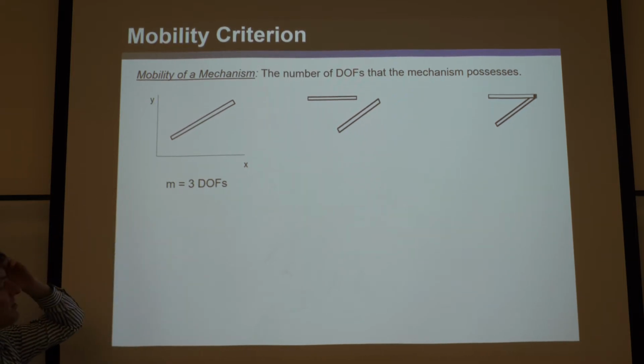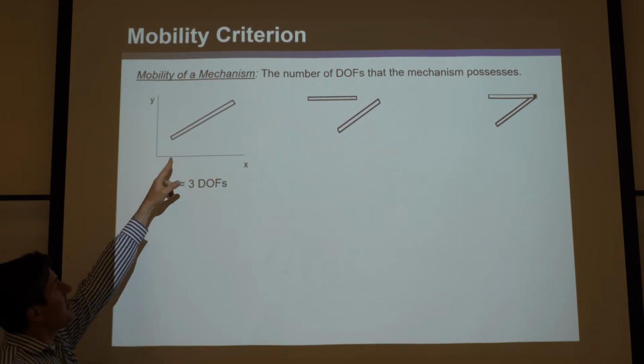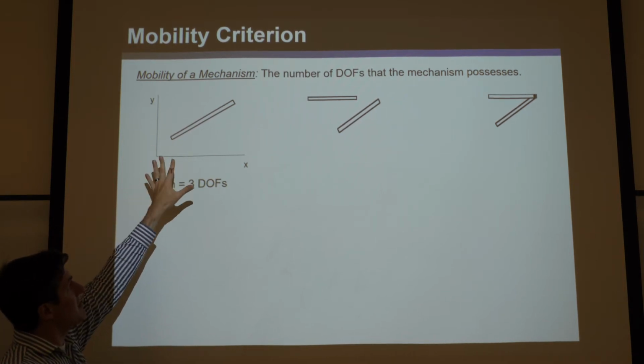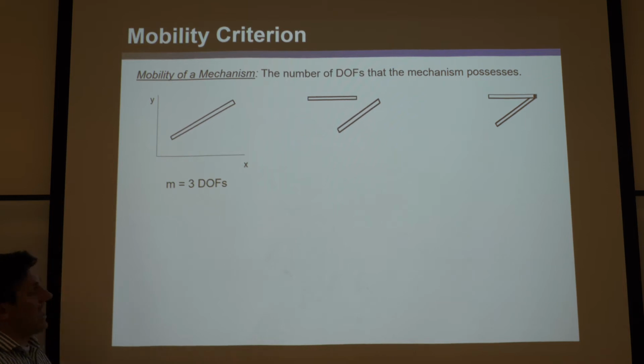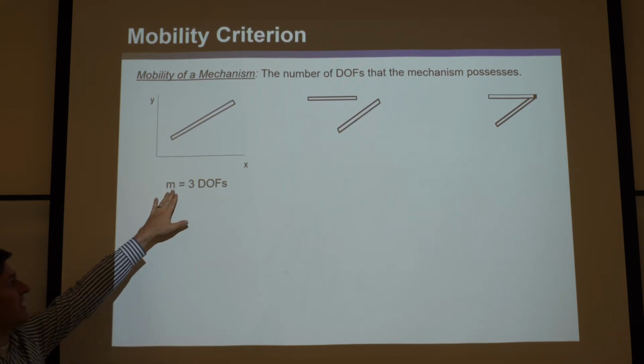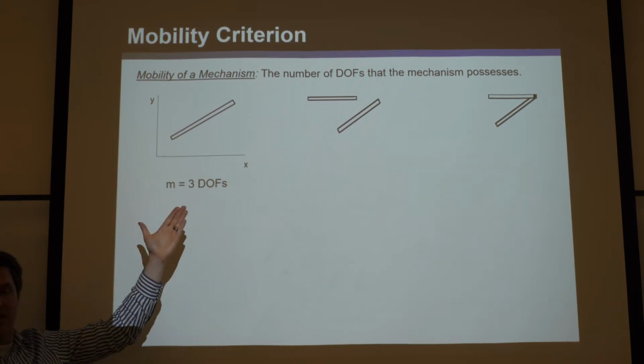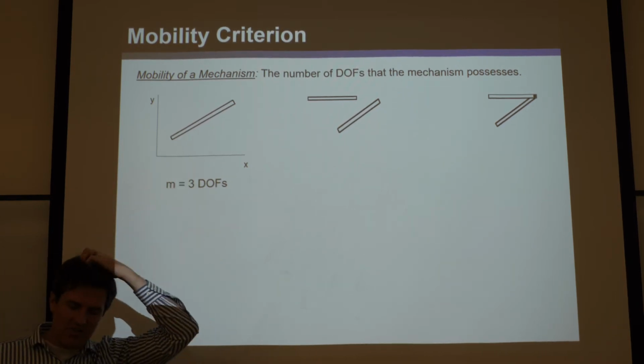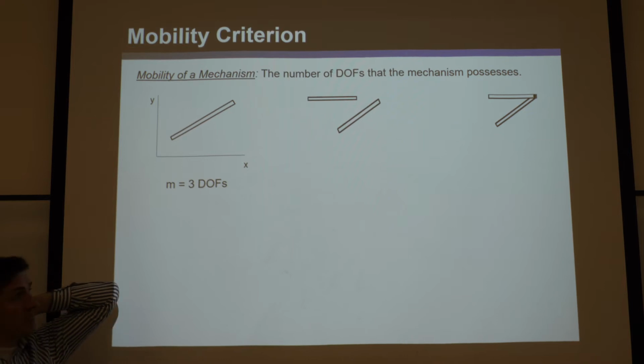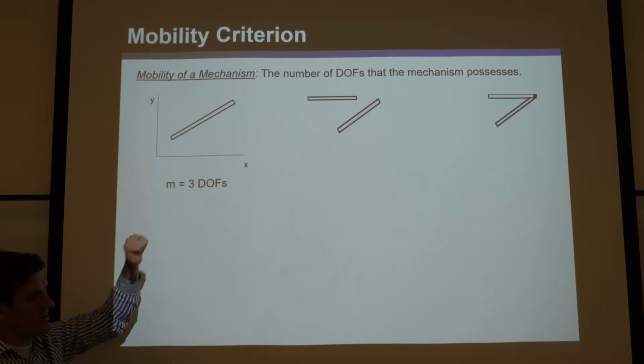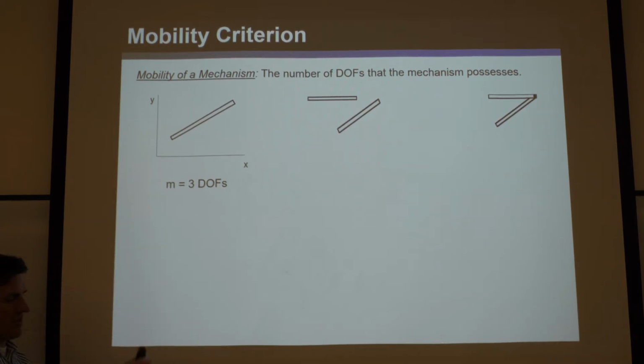and so we're going to just look at things in planar land here with planar mechanisms. So you can think if this is a single rigid body just on a 2-dimensional surface, and there's no constraints anywhere, it of course has 3 degrees of freedom. Its mobility m would be 3, meaning it can translate with 2 independent translations, and it can rotate out of plane, or with an axis that comes out of plane. Of course, it'll always be rotating in plane. All the points on it will be in plane. Right? So, okay. So I told you, 2-dimensional things have 3 degrees of freedom.